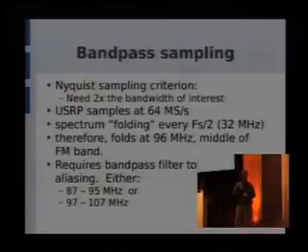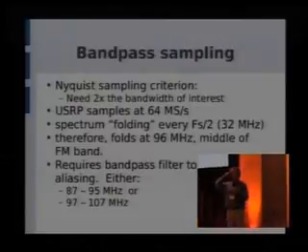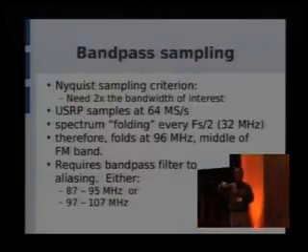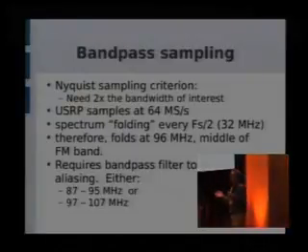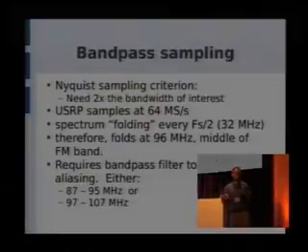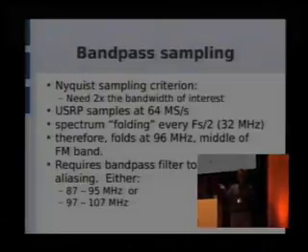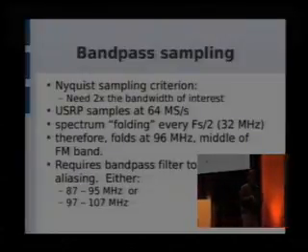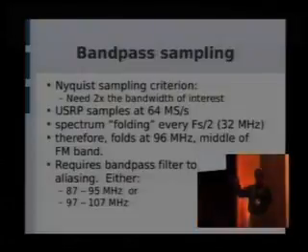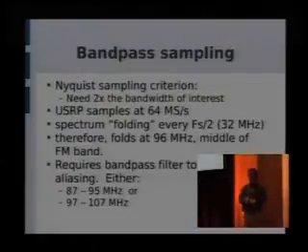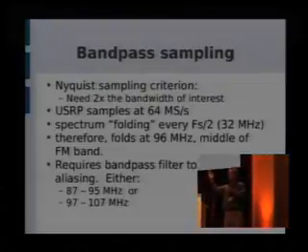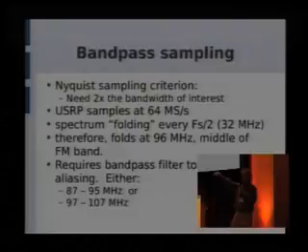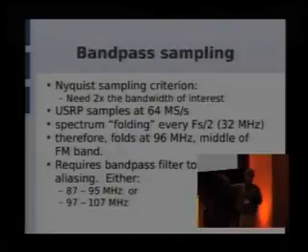So in the cases, like people mostly come out of engineering school, the first time they look at this, they're always thinking of the low pass case, where that means if I have a signal that's 100 megahertz, then I must need to sample it at like 200 megahertz or 250 megahertz. Well, if I were trying to capture everything from 100 megahertz and down, that's true. But if I'm only trying to capture some stuff that's centered at 100 megahertz, but maybe is a few megahertz wide, then I don't need to run that fast.